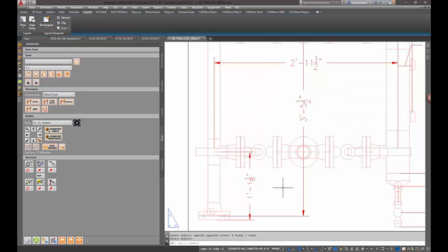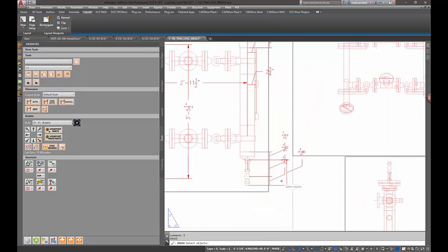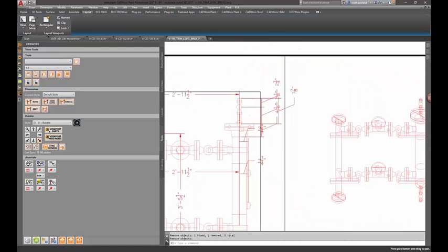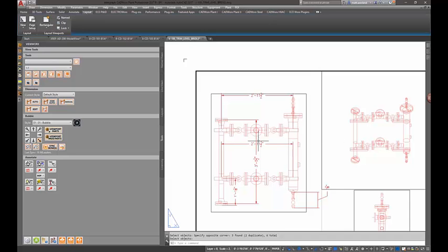That's going to be easily taken care of by just going from point A to point B with installations. We do want to get an overall on this side, so let's clear out some of these components here. We've got some basic dimensions in there. We'll go into our edit dimension mode and start stretching these out to clean up a little bit.